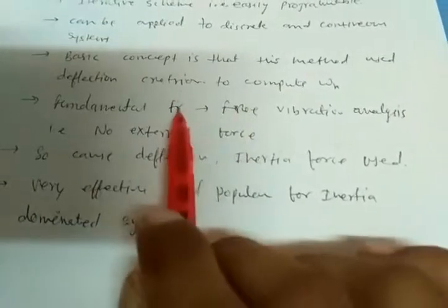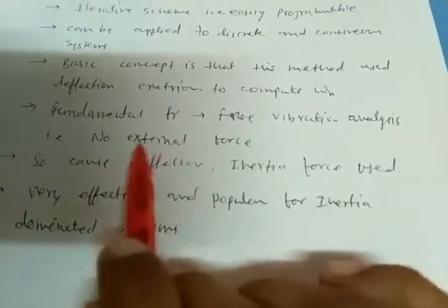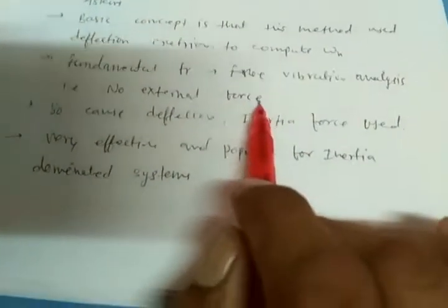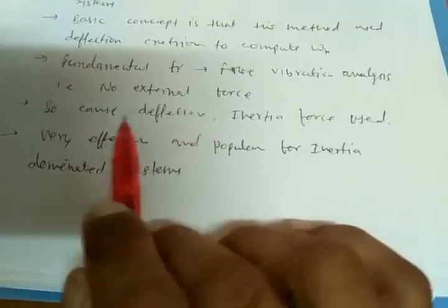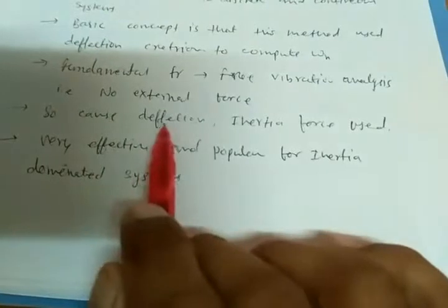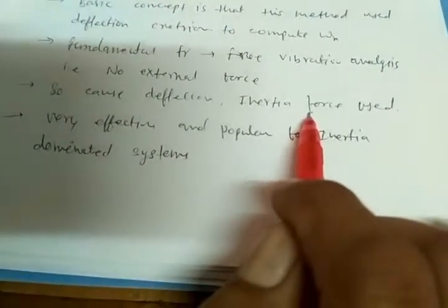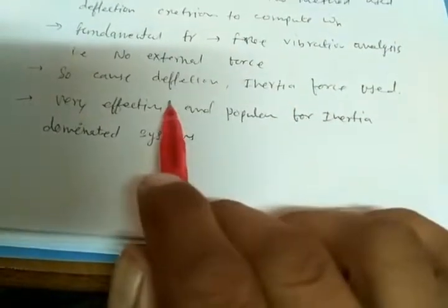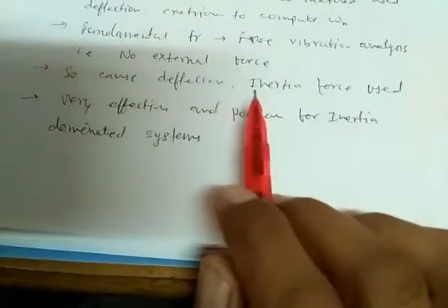It gives the fundamental frequency for free vibration analysis. So there was no external force, and to cause the deflection, as there was no external force, we have used inertia force as the force. And this method is very effective and popular for inertia dominated systems.